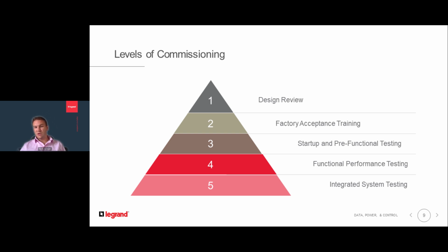You kind of jump into level 4. And I always describe level 4 as a more selfish type of inspection, because you're going from vendor to vendor, and they are basically selfishly looking at their own equipment. They're looking at functional performance testing of that equipment. With overhead busway in particular, we're going to pull a 2-hour load across that bus. If it says it's going to be 1200 amp busway, you're going to pull 1200 amps across that. It's very, very important to specify that.